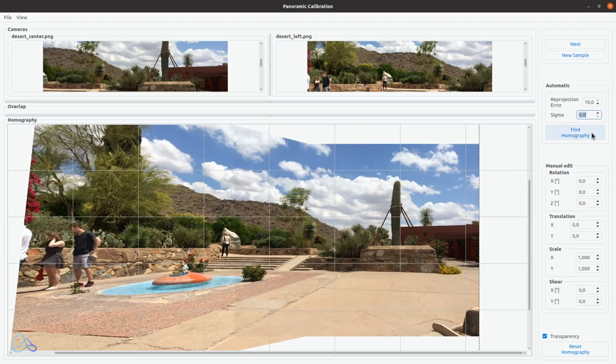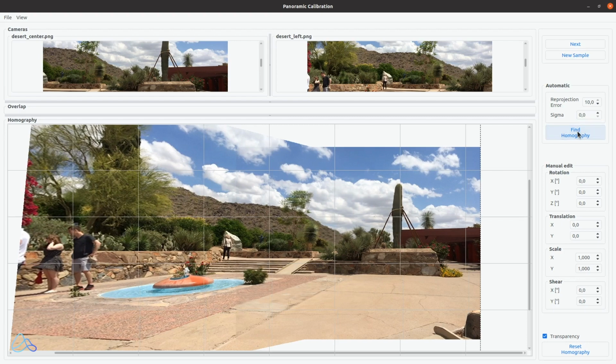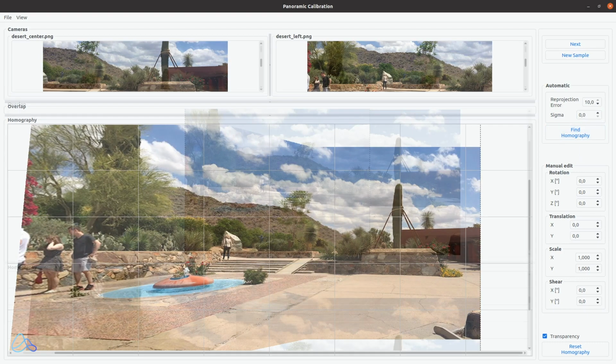Sigma is used for the preprocessing to reduce the image noise. Reducing the image noise allows the algorithm to find better feature points. Big values reduce the noise but also image details, whereas small values remove less noise but preserve image details. Bear in mind that your image may not need any denoise at all to work properly in the first place. This will depend on each specific case.